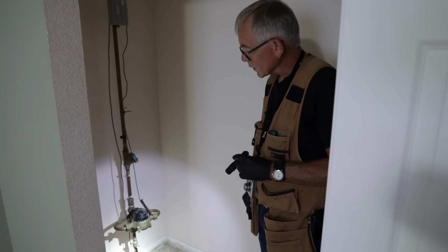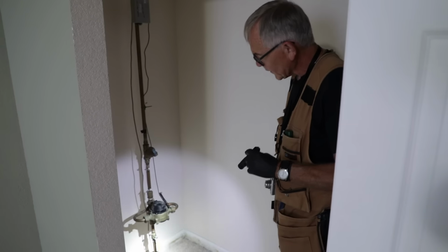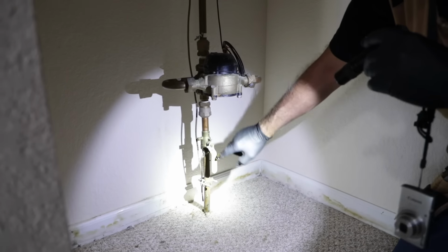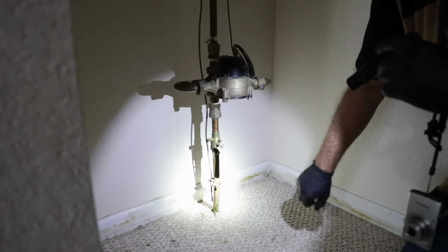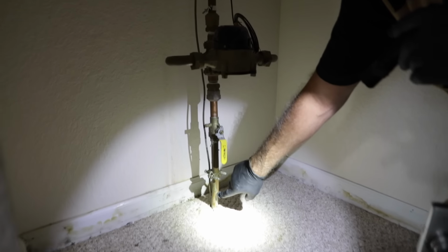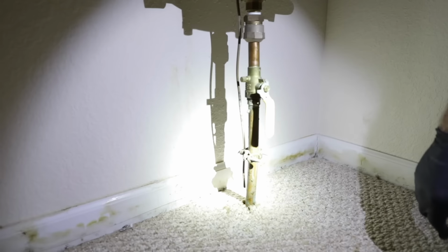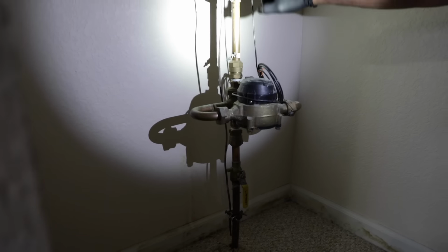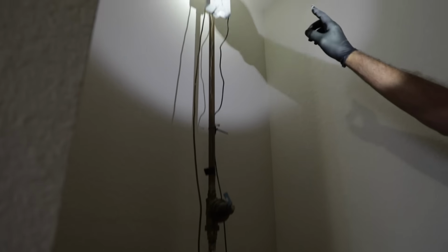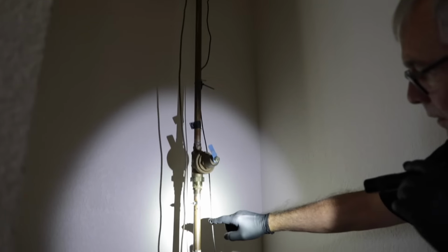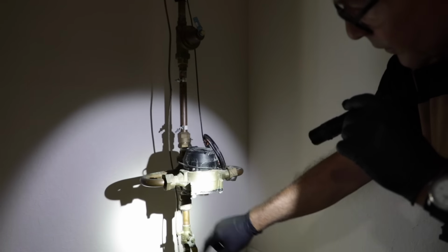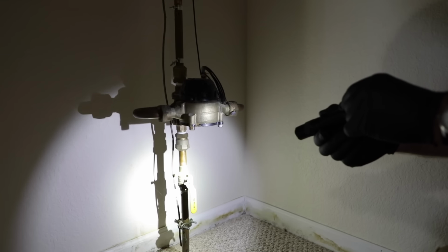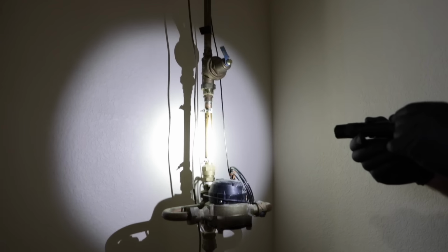And the first thing we're going to do is look at the main water supply shutoff valve. And right down here in the basement, this yellow handled valve would be our main water supply shutoff valve. Our main water supply coming in is copper, 3/4 inch. While we're here, we're going to make sure we have no leakage or anything in the main water line. This feeds the entire house on the inside. Everything looks pretty solid. So we're going to conclude that part of the inspection, and we'll move on to the next one.